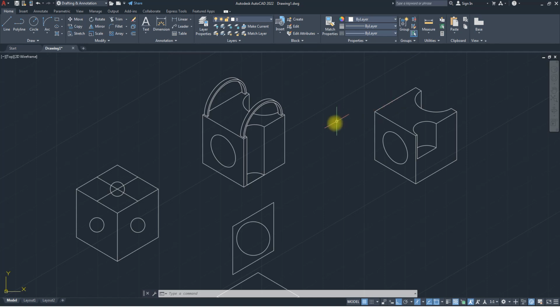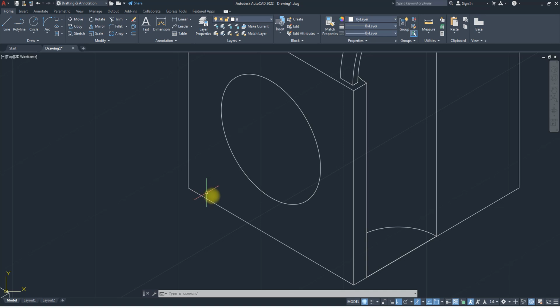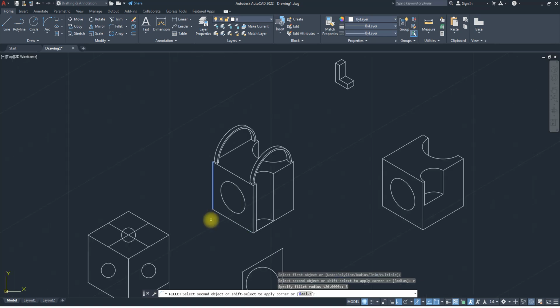Yeah, we can still. I won't show you everything. So, what if we want to create kind of a fillet? You can also do fillet in isometrics now. So, I can decide, okay, maybe this place should have a little bit of fillet. I can run my fillet command. It's the same way you run it, press R for radius, set your radius. So, let's assume we want to run a fillet of radius 20. Pick the first line and the second line. You see that? I think it's too much. R back, make it 8. I have this.